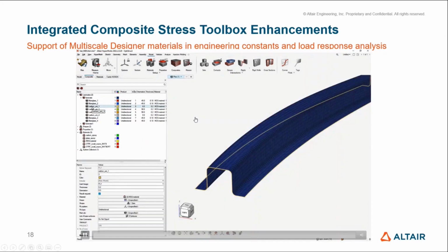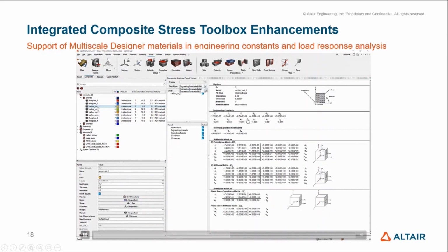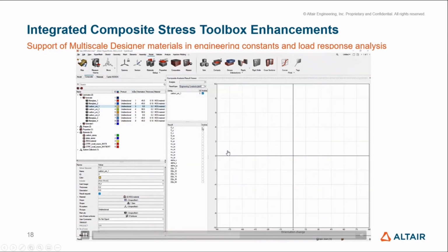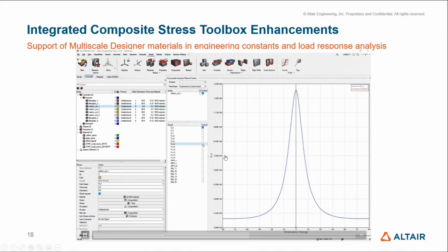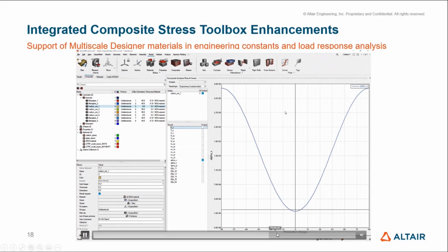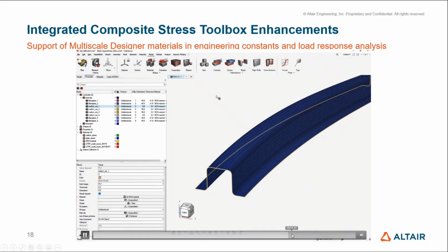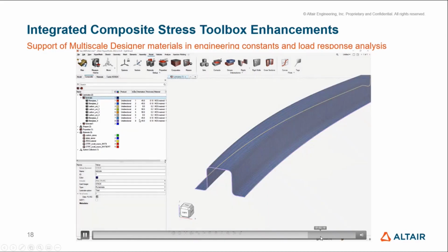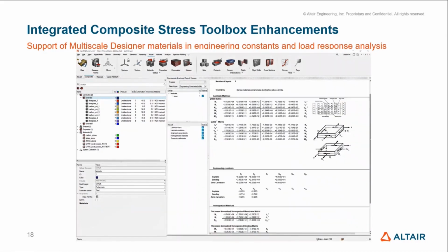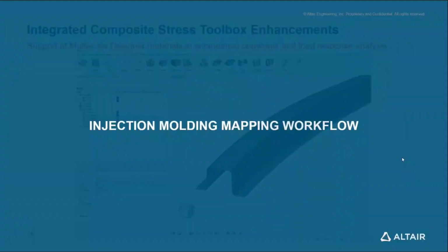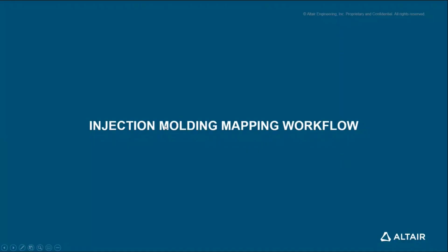And then you can go ahead and use it as if it was any other material, except for the allowables. But now you can see here, I can do a ply analysis. I'm going to get my ply values. I can go review, as with any other, all my values. I can do that same thing on the laminate, and it propagates through. And I can also do load response, just the first ply failure is then not available. And obviously the strength ratio corresponding cannot be available as well.